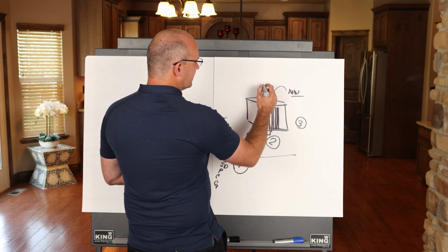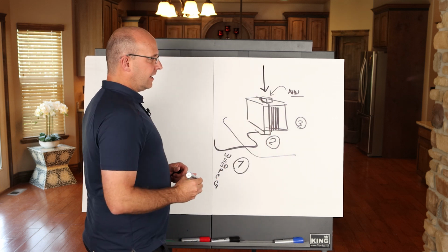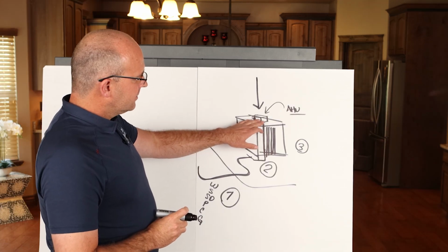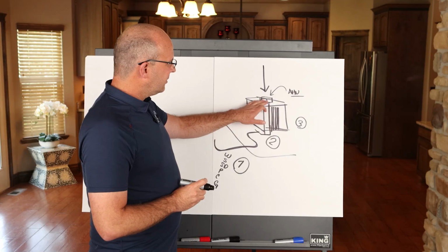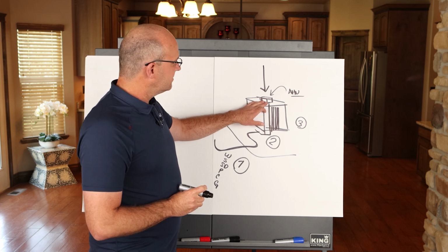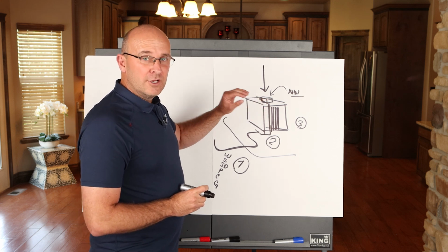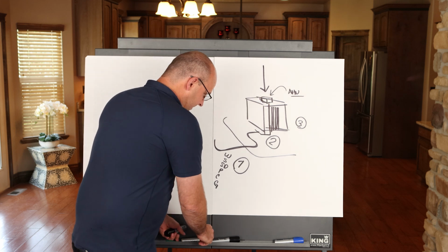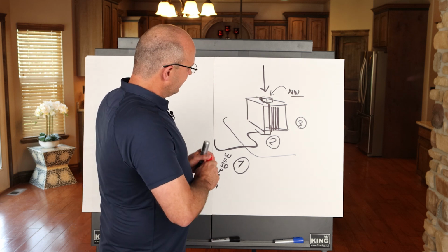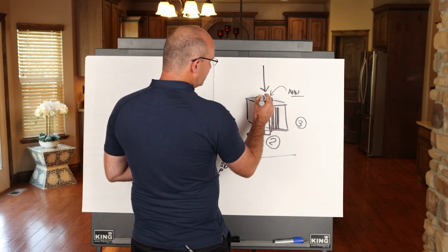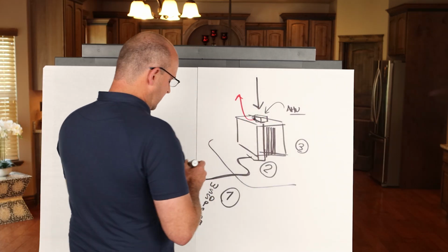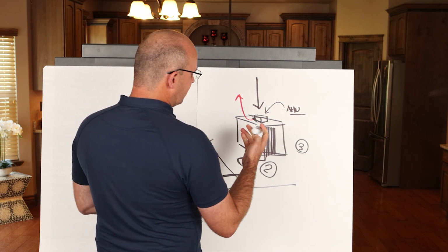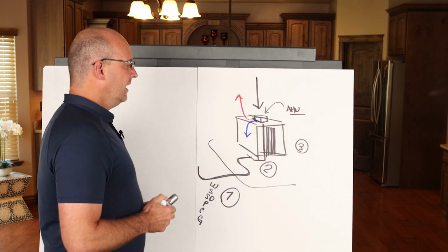The purpose here is to fly in the air handlers and then do your hookup to power, to controls. Make sure you're doing your dry side, wet side connections, doing your mechanical startup, your point to point, and then putting these things in hand. And the typical process here would be for this to exhaust the building, and then also to supply, especially in Phoenix, cool air in the summer months.